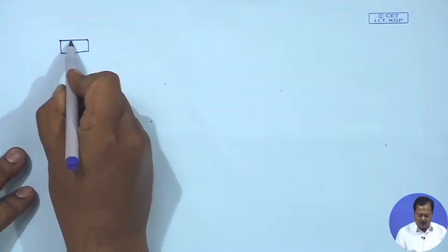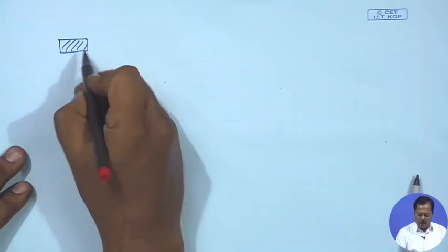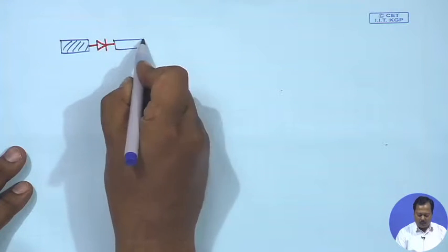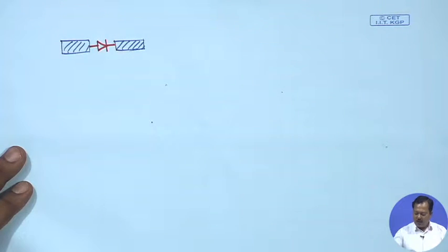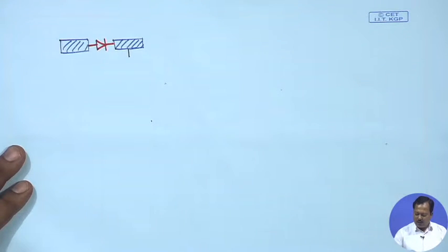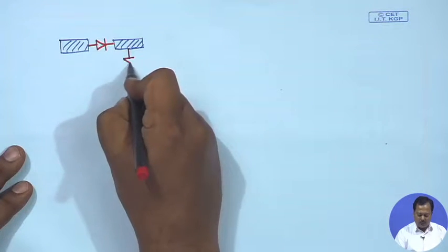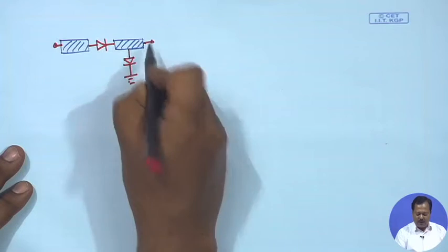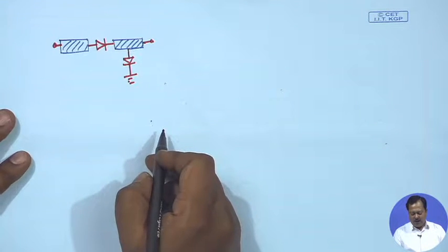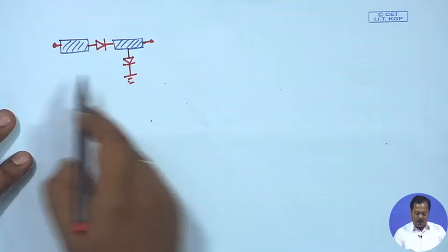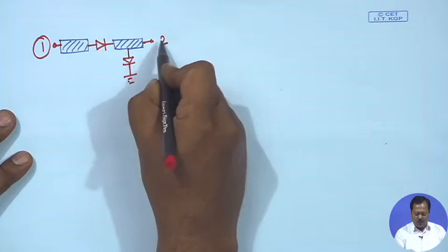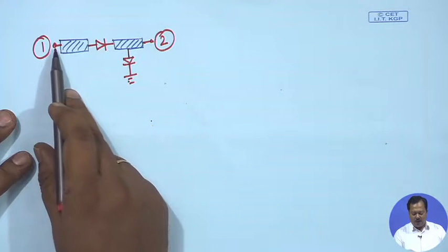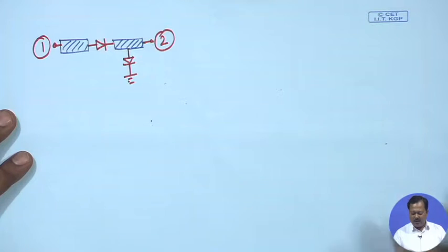This is the microstrip line top view. One diode will be used in series configuration and the second diode in shunt configuration, and together it behaves as a single SPST switch. Now, if I want to connect left hand side to right hand side, when the switch is on, what should be the conditions of the diodes?